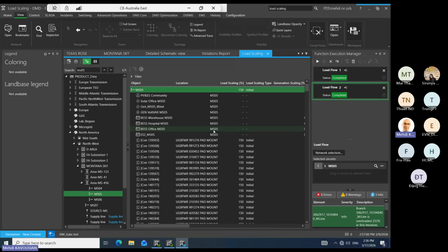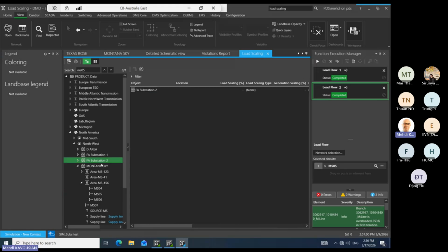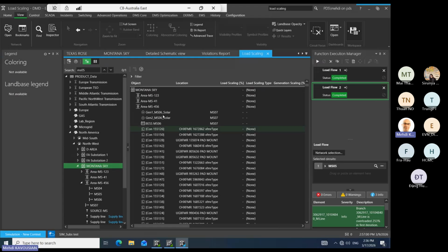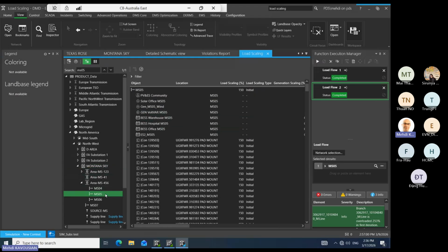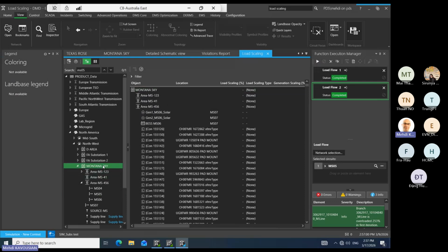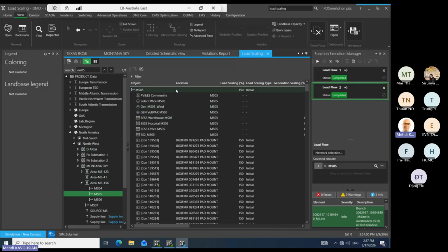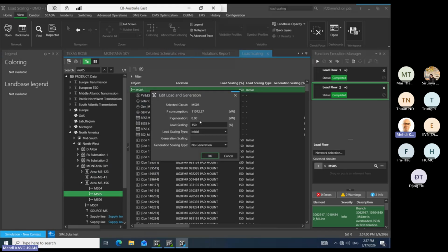That is the what-if studies that I was talking about generally. And this scaling could be done on different levels. Like I did it on the feeder level, right? And it shows it here, so it's 100%. And you could do it on the substation level, the whole substation, everything. So you could go up to wherever you want. The other option I have, sometimes scaling, I like this one because it's kind of comparable. You could say daily curves multiplied by daily curves.